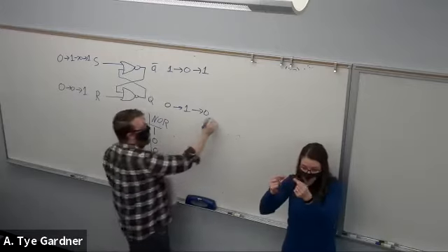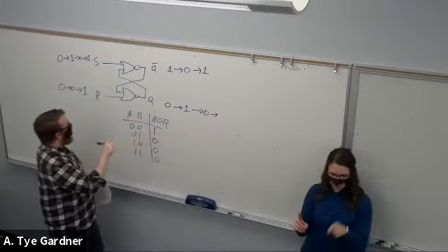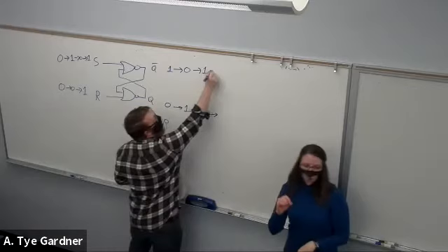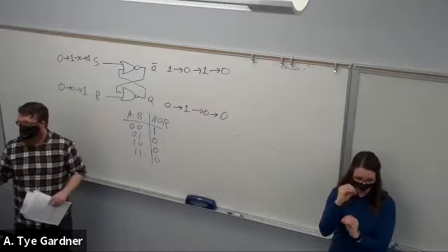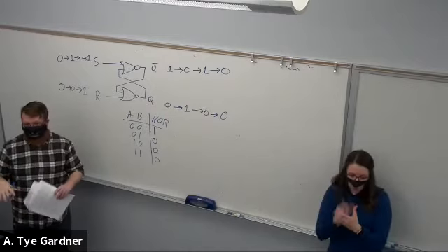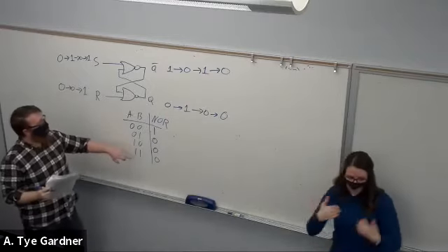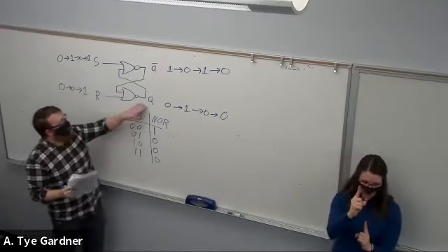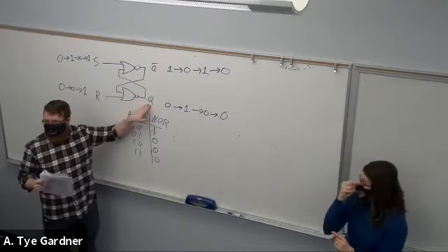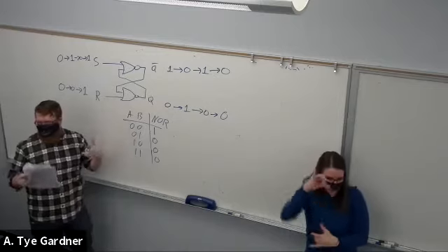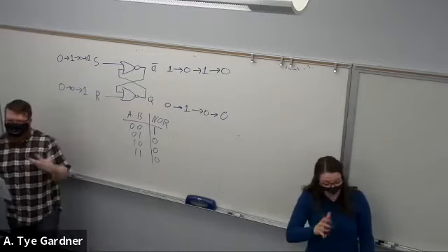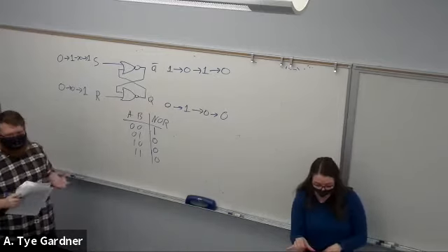Should it be 0? Oh, sorry, 0. Sorry, yeah. I did that reverse, 0 and 0. So we get zeros on both because of 1s. So we're no longer Q and Q bar, right? They're the same. This is okay, kind of. We're not supposed to do it. It's really treated as an undefined state.